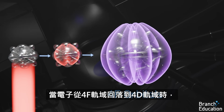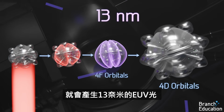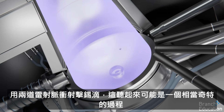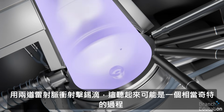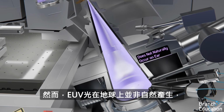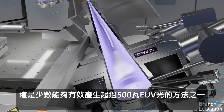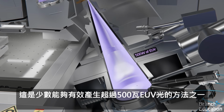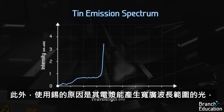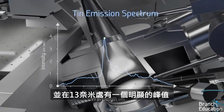When electrons drop back down from the 4F to 4D orbitals, 13 nanometer EUV light is produced. Shooting two laser pulses at a droplet of tin might seem like a rather obscure process. However, EUV light doesn't naturally occur on Earth, and it's one of the few ways to efficiently produce over 500 watts of EUV light. Additionally, the reason for using tin is that its plasma produces a wide range of wavelengths with a clear peak at 13 nanometers.